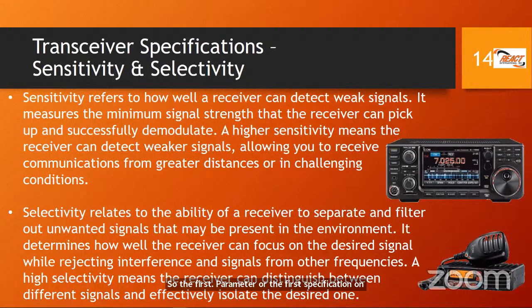Now, you probably already guessed or natively know what sensitivity means. It's in the nature of the word. How sensitive is it? Can it receive a weak signal? Or is it not as sensitive, so therefore it does not receive a weak signal? So that's what sensitivity means, the ability to receive a weak signal. And that is one of the things that defines a good quality transceiver, one with a receive section that is very sensitive.